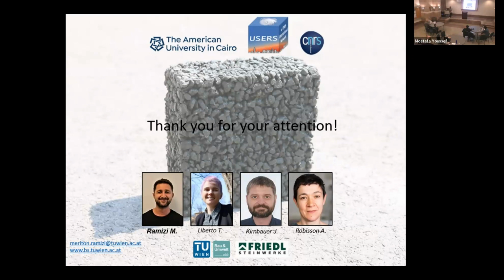First of all, when I started to investigate the topic, the idea was to increase the porosity of the sample as much as we can. As I said, this is just my master thesis. After I finished it, I read a paper that using a tiny amount, 5% or 10%, of fine sand may increase the contact points between the cement paste and the larger grains, as well as silica fume. But in our case, as you saw, the silica fume had no significant impact on improving the mechanical properties.